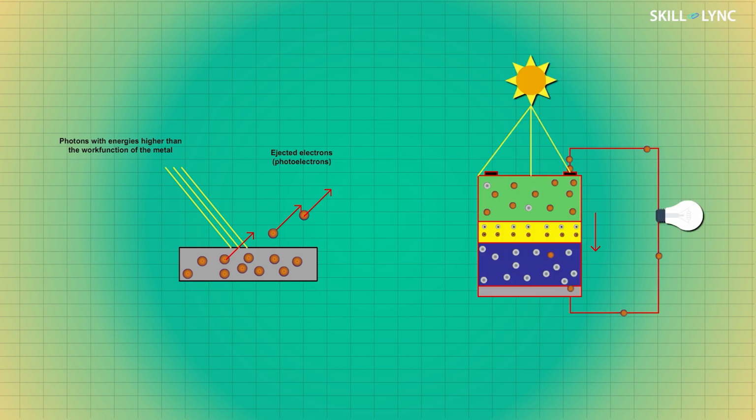A photovoltaic cell has two thin regions, namely N-type and P-type. The N-type is doped with an element having 5 valence electrons, thus rendering one electron free to be donated and forming donor ions, while the P-type is doped with an element having 3 valence electrons, resulting in the formation of acceptor ions. As a result, an internal electric field is developed. When the sunlight falls on the cell, the electrons get excited from that energy and move under the electric field developed between two electrodes, thus producing a current.